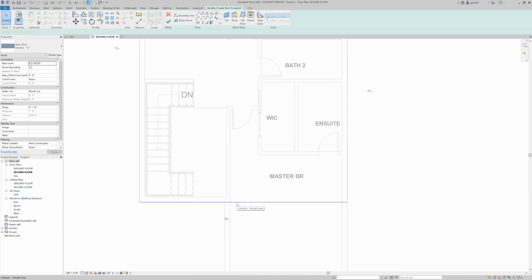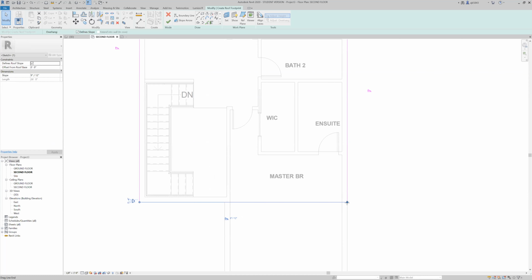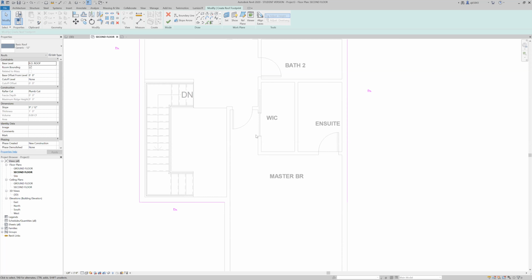So sometimes when you're getting started with this, it's a little difficult to think through, and oftentimes trial and error is the best way. As we were doing this, it took us a couple tries to get this to look the right way. So essentially, if I recall correctly, what we did was created an additional line just to be able to grab a center point because we want to basically center the connection of this roof so that it slopes down into this primary corner here. So I'm just going to use one of these roof lines as sort of a reference line, and we'll delete it here in a minute.